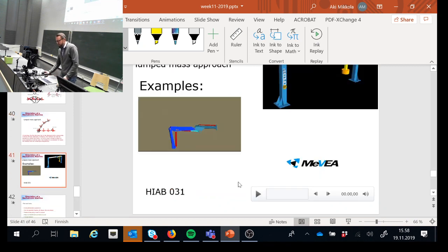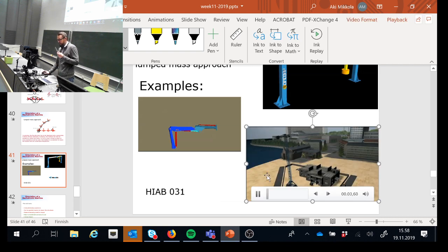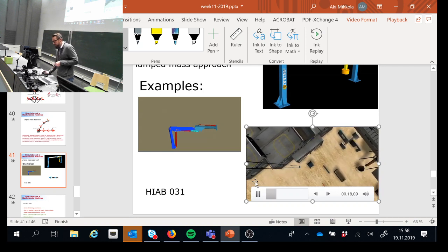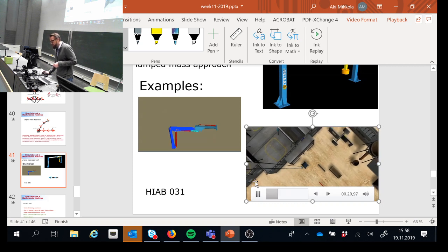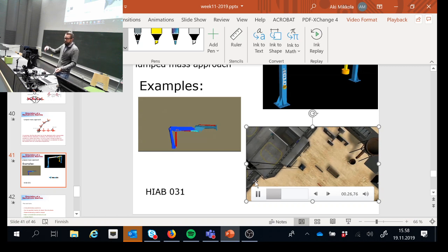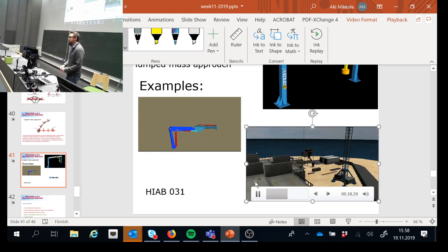Here are a few examples. It's still being used in some cases, like modeling cables. Here is a tower crane, a little bit of a small figure, but there is a cable going down here, so there will be a better view for that. And that's modeled using this simple lumped mass approach. This is a cable or wire rope that I'm referring to. And by the way, this has the string effect too. Once the wire rope is without loading, the frequency is low. And as soon as you load it, the frequency becomes higher. You can clearly see that when you look at that particular detail.